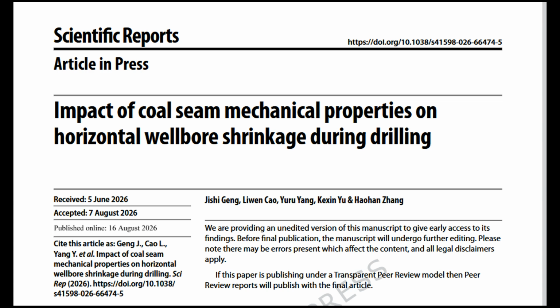Equations 16 and 17 are compatibility equations obtained by integrating the flow rule between the initial and current configurations. They relate the current radii of the wellbore and the plastic zone to their initial values. The exponents involve the dilatancy coefficient, meaning that the deformation is not only large but also accompanied by volume changes.